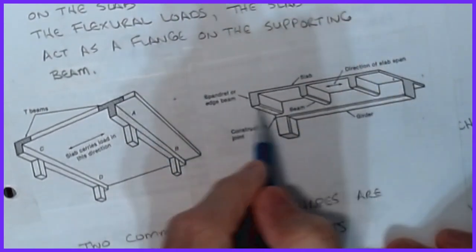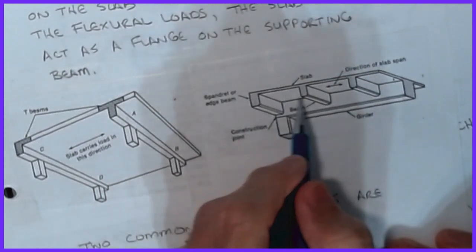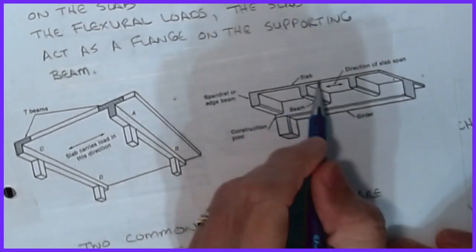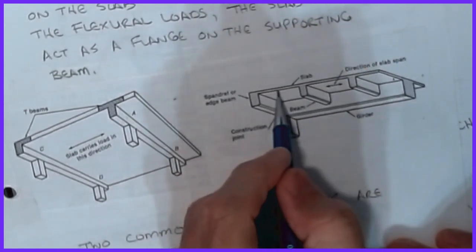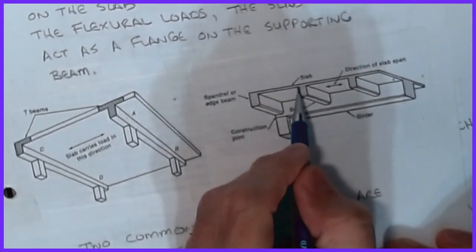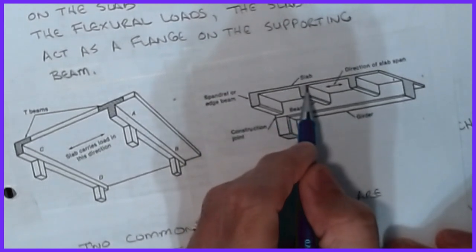And so all three of these guys kind of work a little bit together in their behavior, okay? So what happens is that we've got to take into account, well, what happens if I only have one beam by himself, that I don't have these other two sides? Because what the slab does, think about a positive moment. I'm getting a compressive force in the top of this beam that's wanting to push on it. And if I push on it hard enough, then our basic mechanics says that I could buckle this guy.